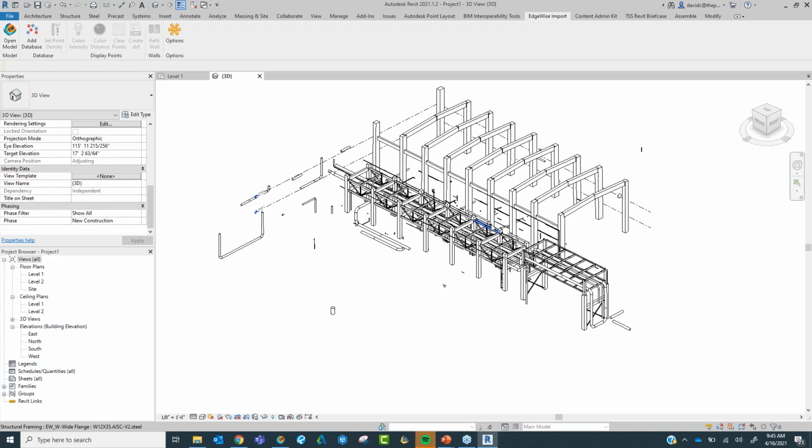So one, looking at the scanner that you're using and just viewing that scan before you finish it and store it before you essentially break down, go to your next setup point. But also getting back to planning, like looking at these problem areas, like what do you want to concentrate on? What are you trying to take into Edgewise? Is it going to be this complex piping system? Is it going to be this structure? Or is it going to be these pumps or whatever it is?